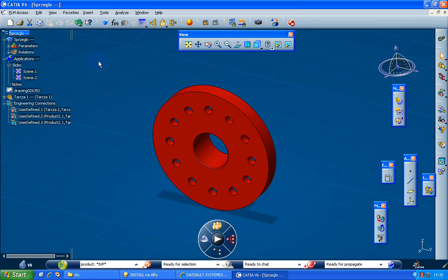Here I can see that I have only assembly or product, right? But I can have as well 3D part, because 3D part can include the 3D shape and drawing. This is important. What we call V5 part reference is called 3D shape, under the representation category, and drawing remains drawing, but here drawing can be seen in the tree of your 3D model.